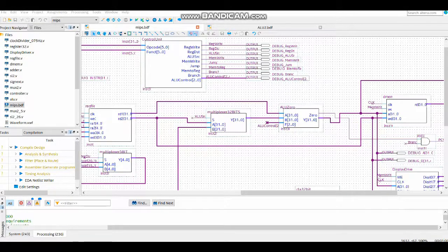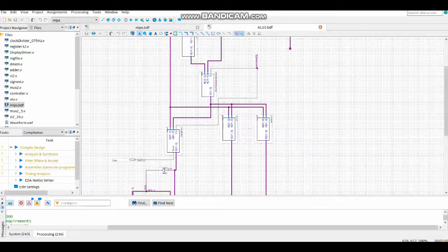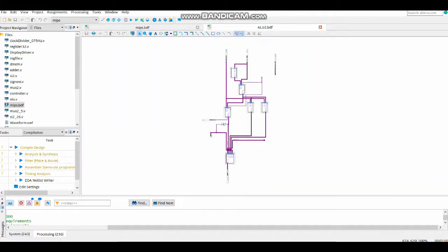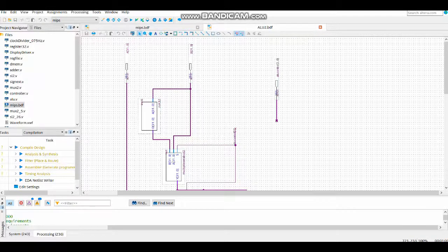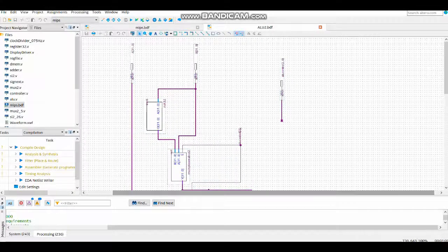Hi, I'm Muhammad Ali again. I'm going to explain more on the ALU, which we also use in our single cycle processor. The ALU is an arithmetic logic unit that combines a variety of mathematical and logical operations into a single unit. As I said, the ALU is capable of computing a variety of mathematical and logical functions, such as operations needed for the MIPS core instruction set, which are add, subtract, and, or, zero test, comparison. You get the idea.